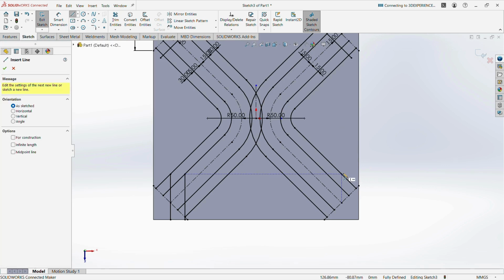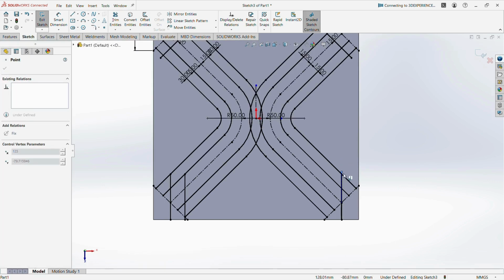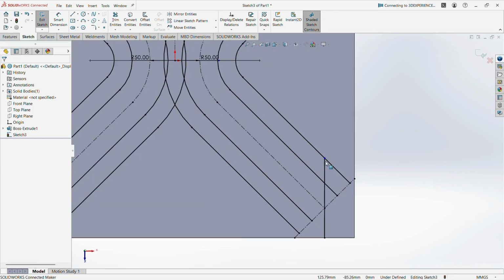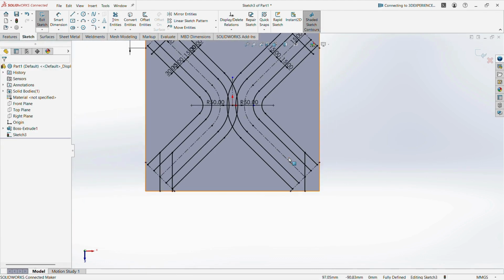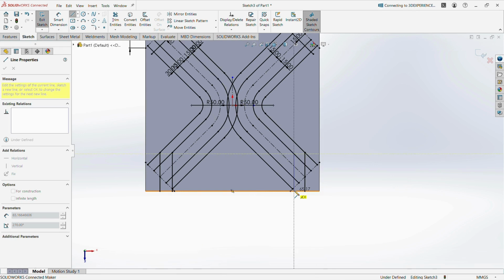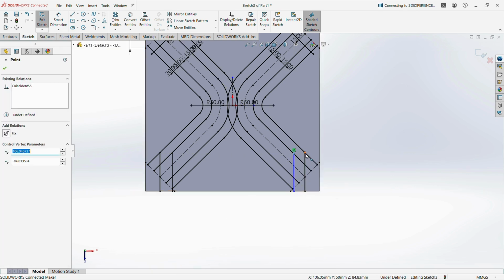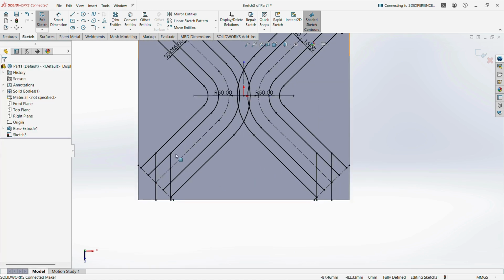Draw another opposite line from this opposite area. The first point is fixed at the top of its area using a coincident constraint. Next, draw another line profile, same as the opposite one. Draw one vertical line again, selecting both points and using a horizontal constraint to fix it linearly.